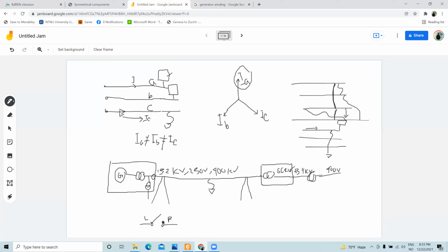So when the circuit breaker opens, as the voltages are oscillating between these parts, you will have a transient voltage until the oscillation damps out. In the first class we have seen it. If we have an RLC circuit, the RLC circuit will damp out this oscillation eventually. But during this damping process, there will be a transient voltage appearing across the breakers.